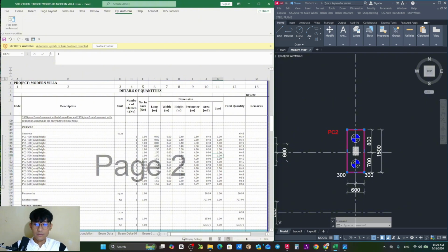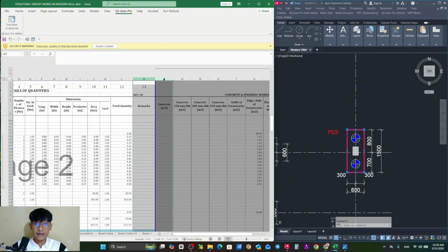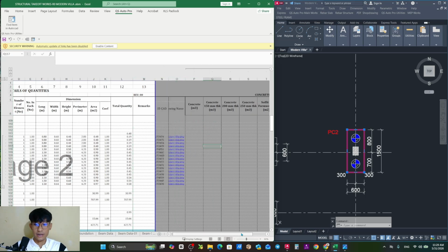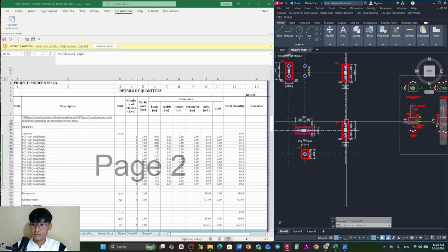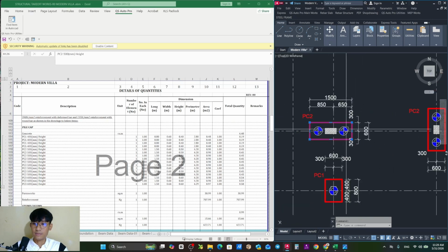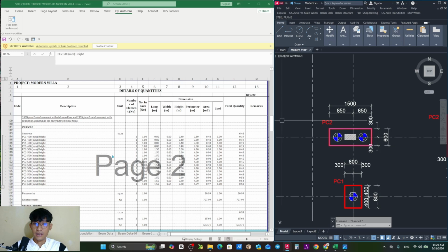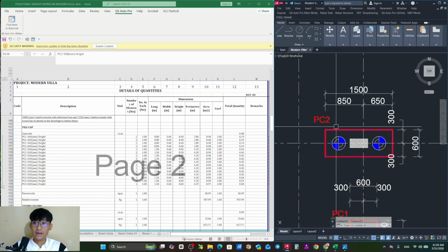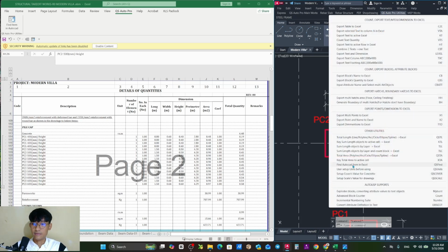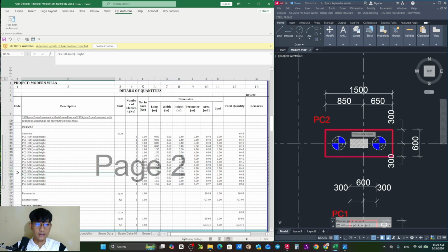Okay, and one more thing, let me unhide the reference code that you can see. I'm going to show you a magic one more. All right, perfect. If I want to know where this pile cap is in our Excel, because there will be a design change, okay, from the height, let's say 400 to 700, all you need to do is go to utility and then find item, and then select on it. You can see it so clearly: there will be PC2, the height 500. If it changes to 700, just type 700 and we will get the new quantity.